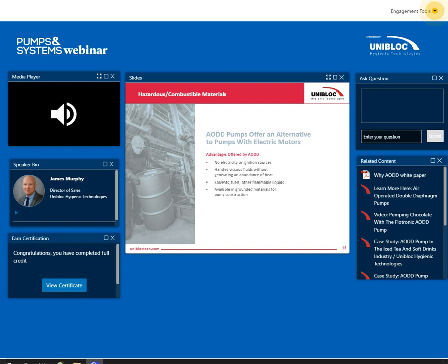And then on the other side, for pumping things that are flammable, although I said there's no true ignition source or electric motor, we do recommend that you use a stainless steel or aluminum pump that can be grounded. There are even some manufacturers on the industrial side that offer a groundable thermoplastic pump, such as polypropylene that's been impregnated with carbon, which can be grounded as well. So some really nice versatility in terms of the different types of flammable or combustible products for different industries, whether it's food and beverage or the industrial segment.